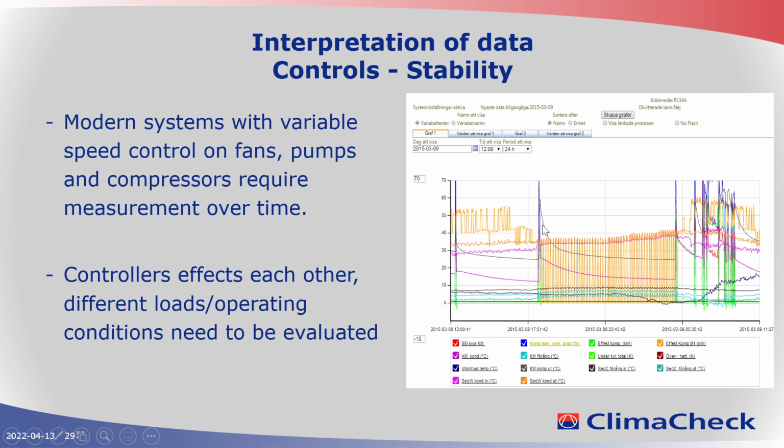But then when they shut down the ventilation at night, the capacity decreases. Then the controller cannot handle this. It's cycling on the 10 minutes restart delay, so it does not allow the system to start more than once until it has been 10 minutes since the last start. So it starts for 1 minute, and of course during that minute there are no changes on the return of the water, but it still shuts off because the supply water decreased. Then it cycles like that.